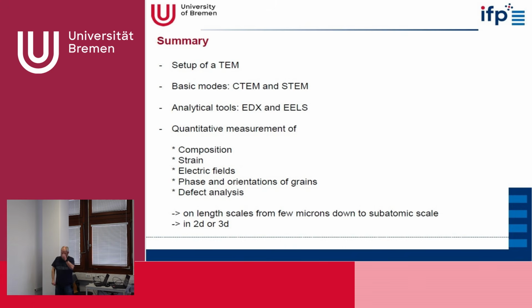Yeah, with this I'm basically through the presentation. And then I want to summarize that. So in principle I showed how TEM is built up, or the setup of a transmission electron microscope. I hopefully showed you that there are two different modes that we can use: conventional transmission electron microscopy and scanning transmission electron microscopy. We have different analytical tools available, so we can do energy dispersive X-ray spectroscopy in the TEM and electron energy loss spectroscopy.